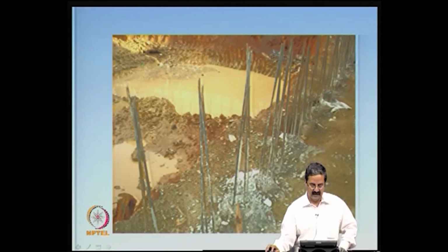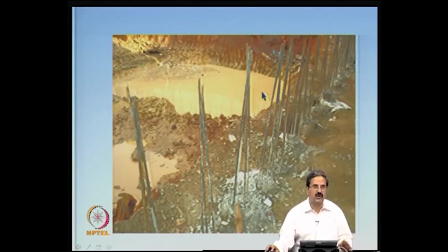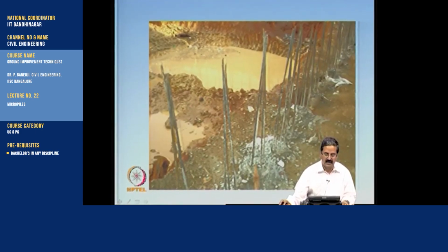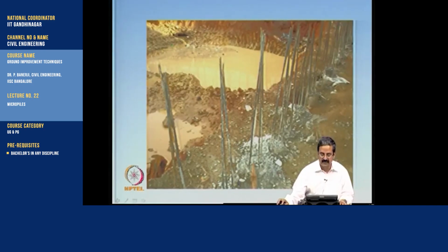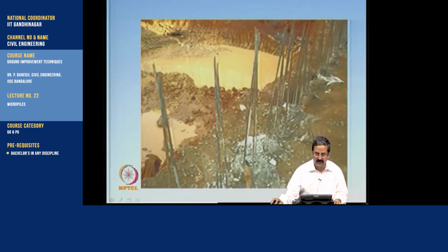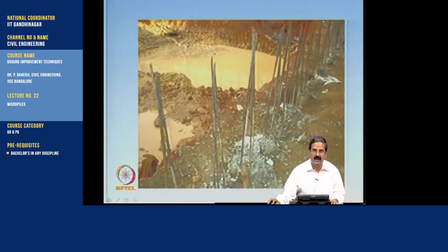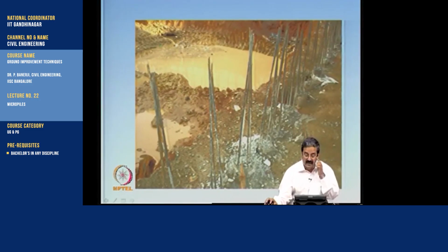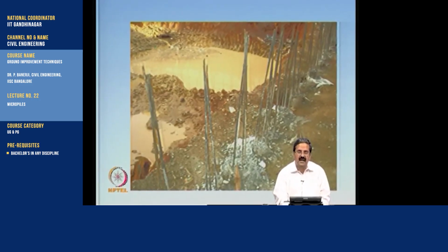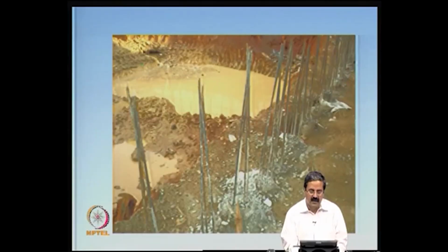You can see the water table is there. When you have a water table, it is not easy to do. For example, it can collapse, particularly when there is a water table at the bottom of the foundation, the possibility is that it can collapse, right. So, there you can see all the micropiles which have about 1, 2, 3, 4 members, and then they provide enough shear resistance.